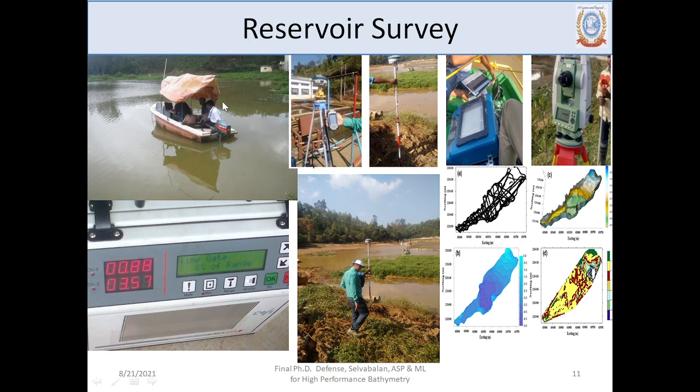This particular reservoir was very interesting because based on our measurements, the reservoir actually got dredged. So here you can see the dredging activities happening. This is a float and suction type dredger with a pipe. It is sucking the sediment material and then pumping it out. After dredging, we verify the bed level change using an RTK GPS. As I told you, RTK GPS gives the elevations also at centimeter level accuracy.